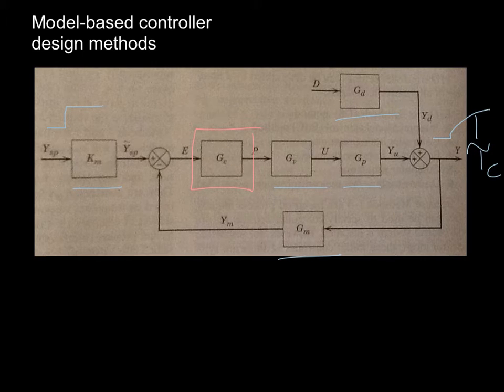So this is a lot the same as the previous design problem, right? We've got a number of known values. All of these things are known, and we're trying to figure out an unknown. And again, we have an equation. We know that the closed loop transfer function y over ysp is going to be all of these forward parts, all of this divided by 1 plus everything in the feedback loop according to our feedback rule.